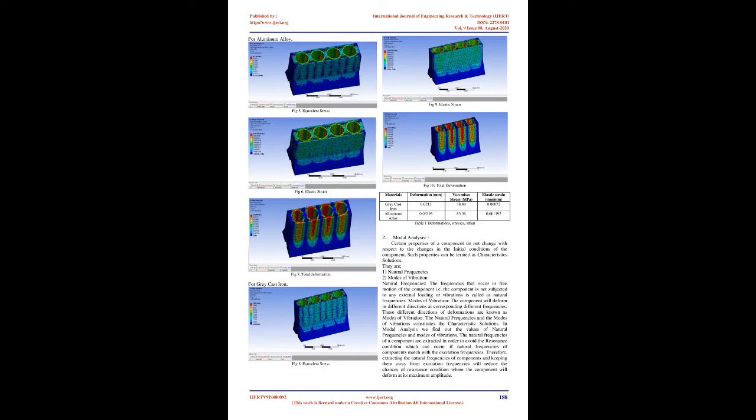There are two aluminum alloys that are primarily used in the manufacture of cylinder blocks, 319 and A356. Aluminum alloy 319 has a composition of 85.8 to 91.5 weight% aluminum, 5.5 to 6.5 weight% silicon, 3 to 4 weight% copper, 0.35 maximum weight% nickel, maximum 0.25 weight% titanium, maximum 0.5 weight% manganese, maximum 1% iron, maximum 0.1 weight% magnesium, and maximum 1 weight% zinc.